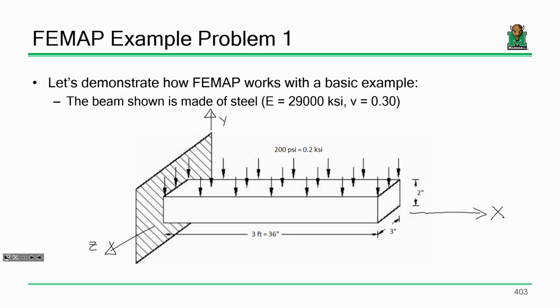That's one piece of advice from somebody who's been doing finite element modeling for quite a while: make sure you set up your coordinate system, your origin, right off the bat. You've got that stuff in your head, your life's going to be a whole lot easier down the road, okay?